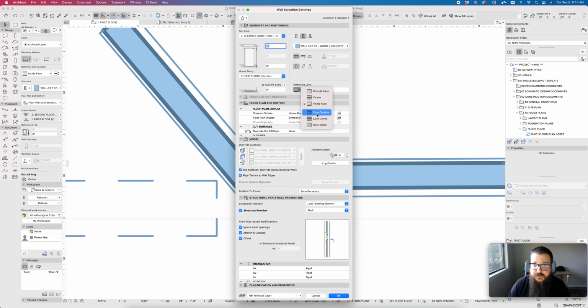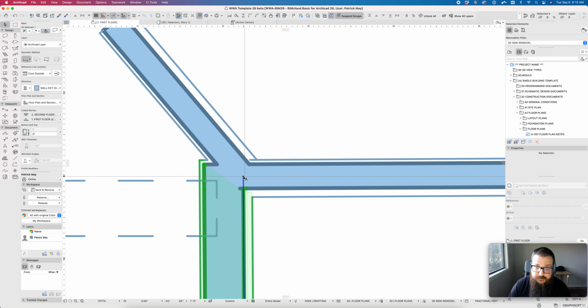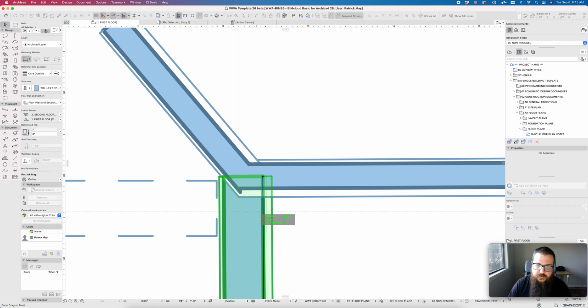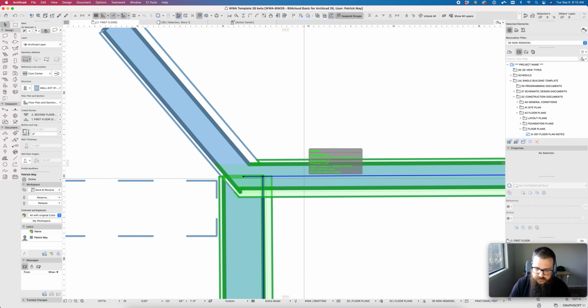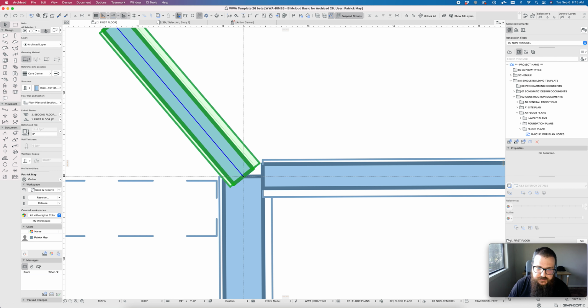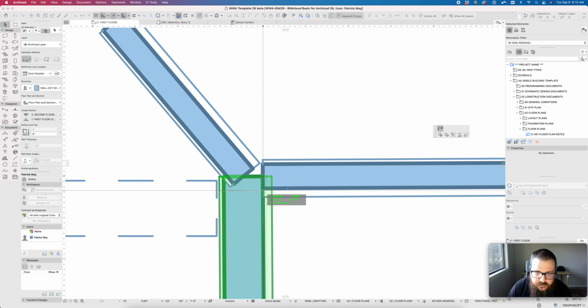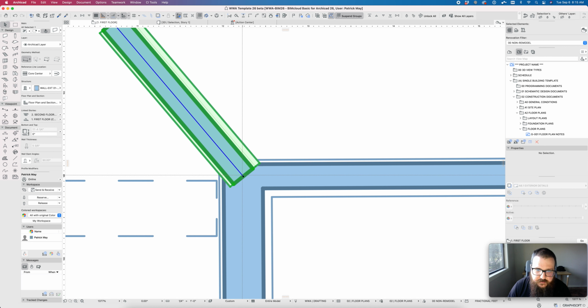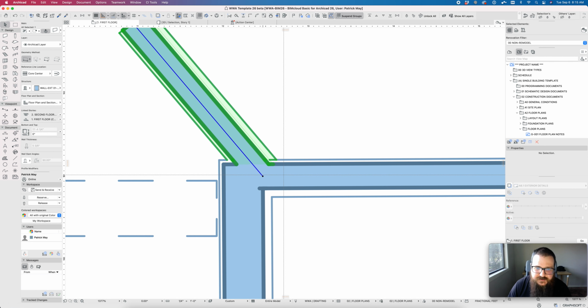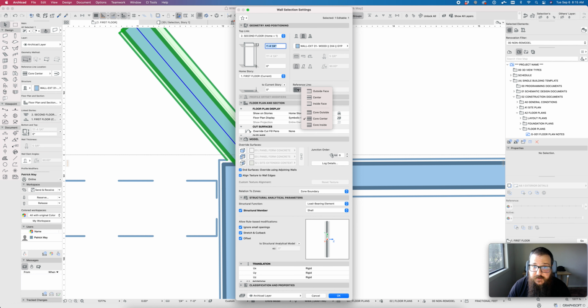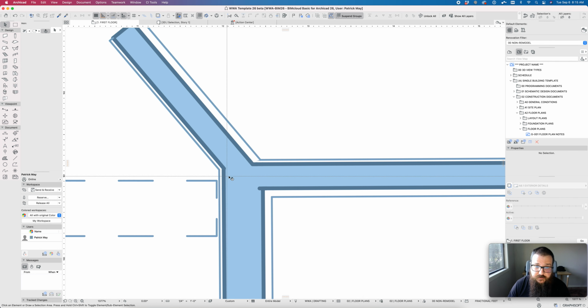The cause for this is largely because the wall reference lines aren't coming together correctly. Oftentimes, you'll need to adjust where that reference line is, even though maybe it makes sense that it's on one side or the other, in order to get these to intersect correctly. So once you get them intersected correctly, that is all the reference lines coming together, if they still are not joining up, bear with me here while I figure that out. Okay. So we get those joining up. This might need to shift over whatever half of that distance is to get that to offset. Maybe it needs to be the core outside in order to shift properly.